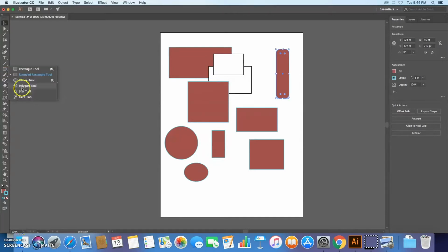Then the other two shape tools we're going to talk about are the polygon and star tools. The flare tool is not really useful, so we'll just ignore it. But the polygon tool will draw shapes with any number of sides. They're always going to be regular shapes, so if you're trying to create something more interesting, then you might need to use some of the tools we'll talk about in later days of this class, or create a basic shape and then edit it. But if you wanted to create, say, an octagon, then you'd use the polygon tool for that. And to adjust the number of sides, you use the arrow keys up and down. So for an octagon, I need 8. Shift will snap it into place so that the bottom side of the shape is perfectly horizontal.